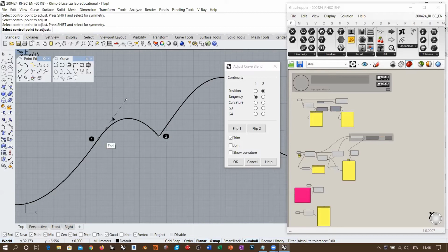So it's the end tangent. And if I do this on column 2, the same thing happens with the start point of the second curve. So this is automatically doing what I was doing by hand, creating a straight line as the continuous line with respect to the final tangent of the first curve, and placing the second control point along that line. This is doing it automatically.